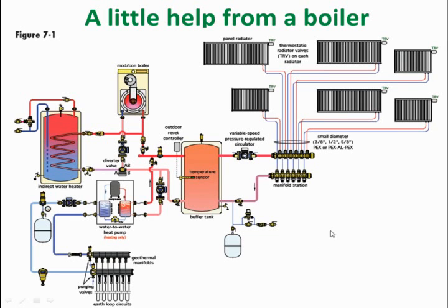So we just put a little bit more control logic to it, as well as some more components in the boiler here, as well as an indirect tank. Let's see, make sure I got everything on this. Yeah, I think the same thing there. There's our boiler trim package and some air vents, a Disco air remover there. And that's just, again, a 3-way Z1 valve there.